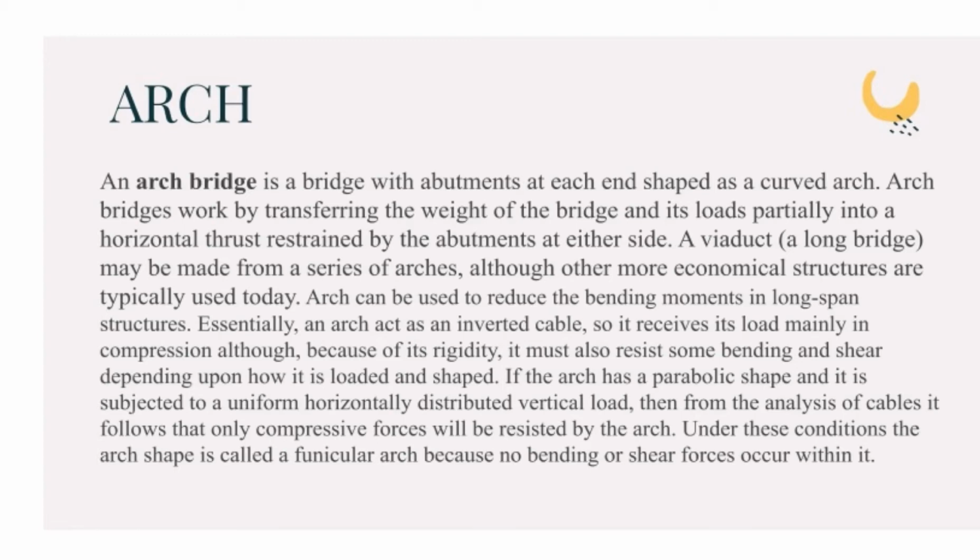A viaduct, a long bridge, may be made from a series of arches, although other more economical structures are typically used today. Arch can be used to reduce the bending moments in long-span structures. Essentially, an arch acts as an inverted cable, so it receives its load mainly in compression, although because of its rigidity, it must also resist some bending and shear depending on how it is loaded and shaped.